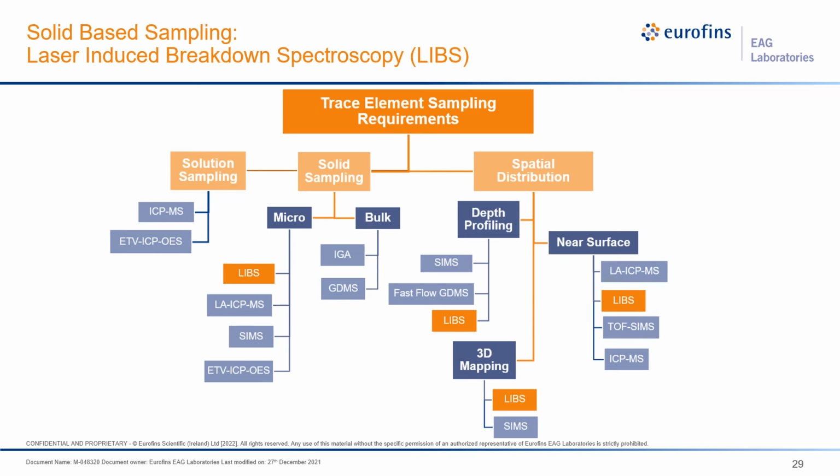The ablated material is then directly measured by an optical emission spectrometer located directly above the sample, allowing for near instantaneous and direct measurement of the elements ablated by the laser. By moving the sample around in an automated cell with a calibrated motor, this approach allows for spatially resolved mapping of element distributions over a much larger area than the initial laser spot.